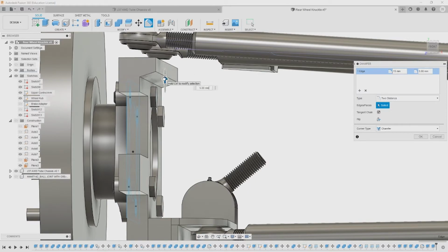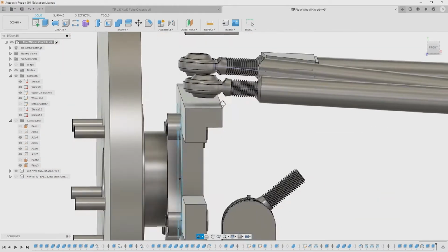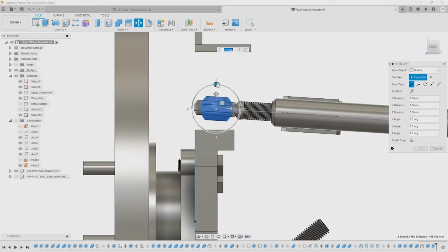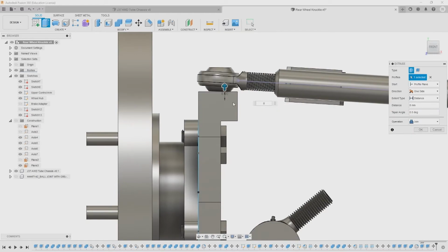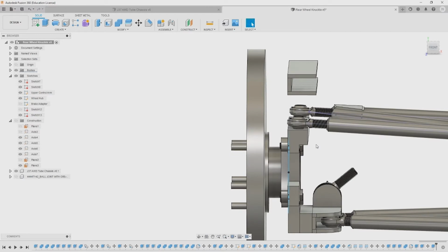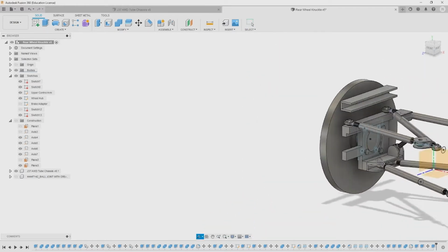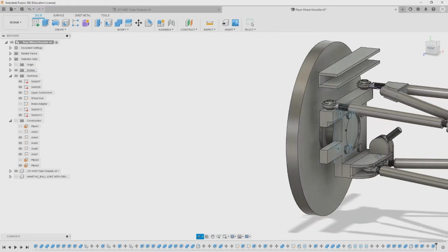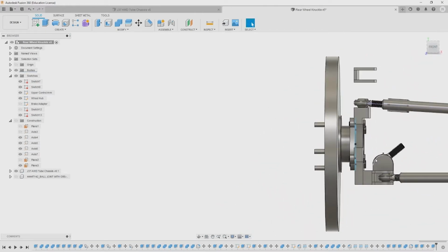So the next step on this, and I'm going to put this off for a little bit in this video, is to drop that fitting fixture that's above it, and that's really just a way to make a captive bolt. So I don't think that needs to be as strong. It's not going to be under as much force, but I am going to make a slightly different version that welds on there. The rod end is 21 millimeters, so there should be maybe a little bit of space to get a TIG welder in there and get it welded on both sides. If I'm not able to, then I'll have to find a different solution, which may include bolting it back together.